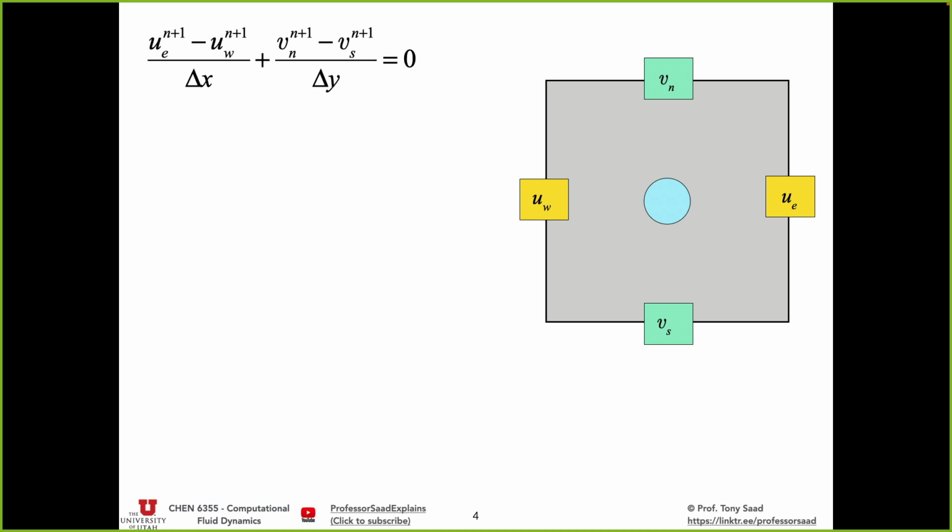If we were to place the velocities at the cell centers, you'd get a finite volume method, but that's still not divergence-free. And you can do that. There are methods; they call that collocated grid arrangement, if you've heard of that. Fluent, for example, does a collocated grid arrangement. All of those collocated methods, where they place the velocities and pressures at the cell center with finite volume, are not discretely divergence-free in the cell centroids. They're divergence-free at the faces, actually, which is not the quantity we want. We want to be divergence-free inside the control volume, because we want everything that's going into the control volume to leave it.